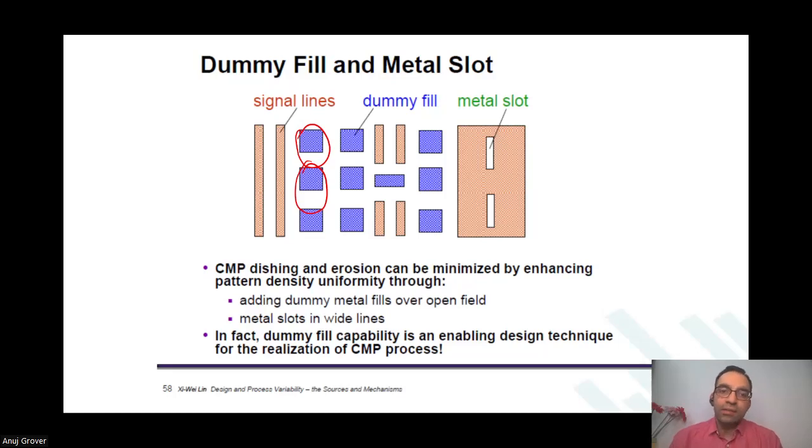So as I said, the dummy fills are added at chip level. So you made the layout of a memory. A SOC designer designed the entire chip around it. After everything was done and the chip was being sent for fab out, at that time they felt that, oh, there needs to be 20% more metal 3 so that density is consistent. That is when they added these dummy fills. Now what will you do?